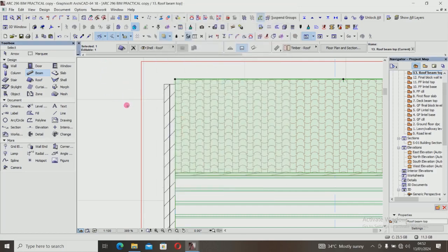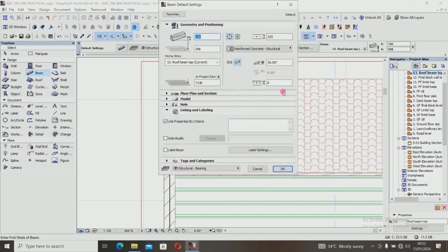Okay. So in that case, you are going to change the angle of this. You are not going to select this, you select this. Select this incline. So the beam is going to be inclined at an angle of 30 degrees. Beautiful. Click OK.